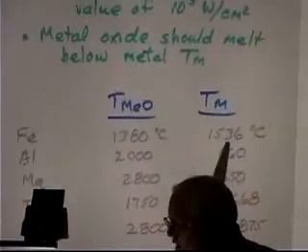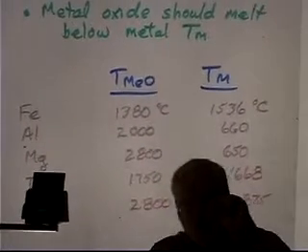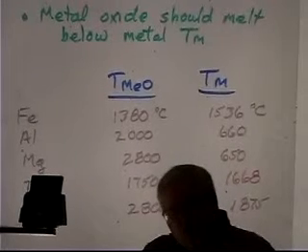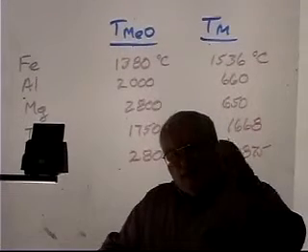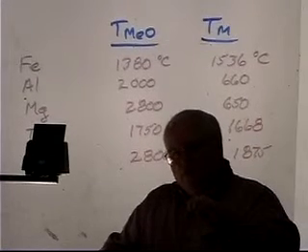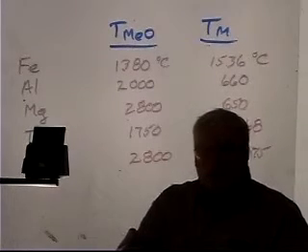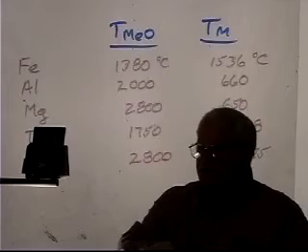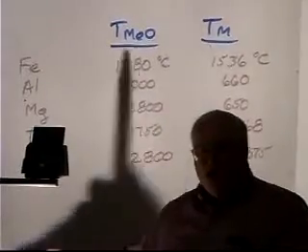And if I bring in a torch that has little pilot flames, oxyacetylene or MAP gas flames, and I put it down on there and I get the surface oxide hot enough, I then have a center jet of oxygen that I have another valve on, another handle on my torch, and when I close that other handle, I get a jet of pure oxygen right down the center. So the jet of pure oxygen hits the hot iron oxide, and the heat blows inside.